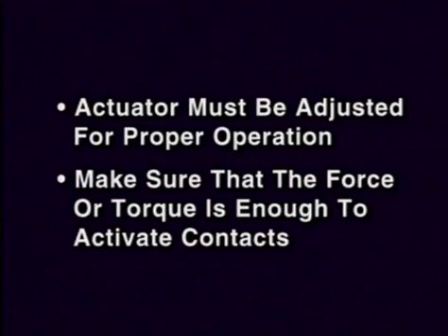You also need to make sure that the amount of force or torque required by the limit switch to detect the movement is enough to snap the contacts. If the amount of torque is limited or the machine travel is minimal, you may need to use a precision limit switch.